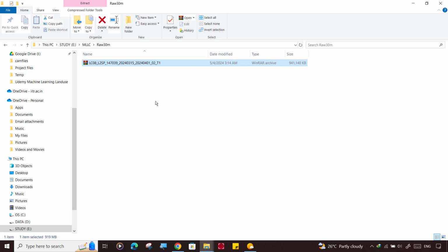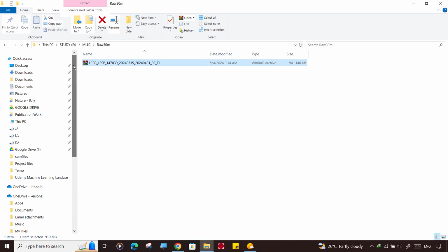Always avoid doing any GIS project from your desktop, because desktop folder paths are very long and ArcGIS does not support long folder paths. We will process this image in ArcGIS. I am pausing this video here. We will process this image in ArcGIS in the next video.